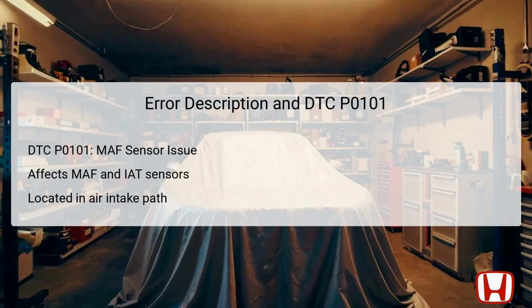The DTC P0101, indicating a MAF Sensor Circuit Range performance problem, signifies that the MAF sensor is not functioning within its specified range. This could mean it's reporting either too low or too high voltage readings. The MAF sensor is essential for the engine's fuel management system. It measures the volume of air entering the engine and helps determine the proper air-to-fuel ratio.